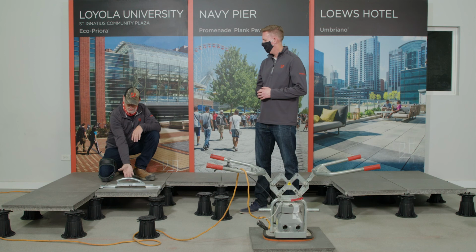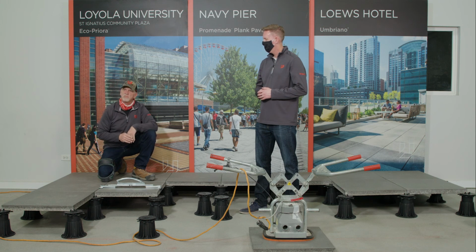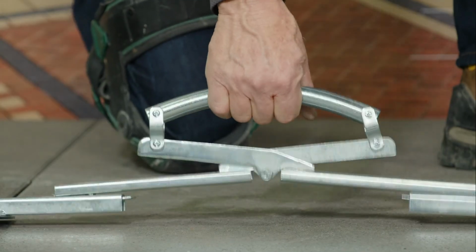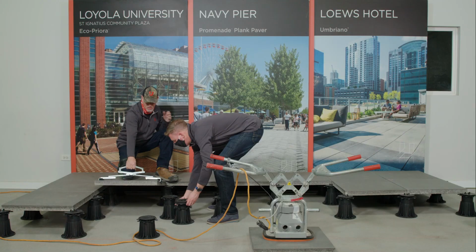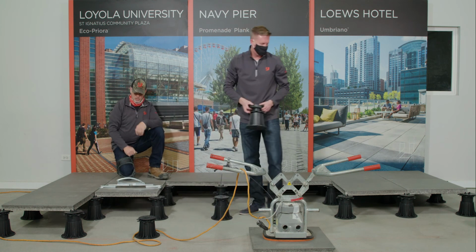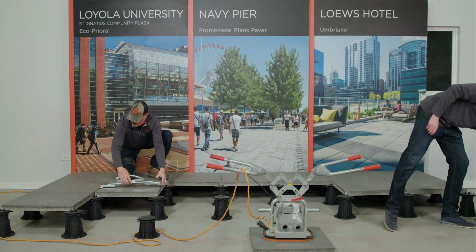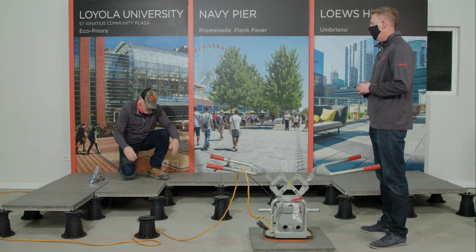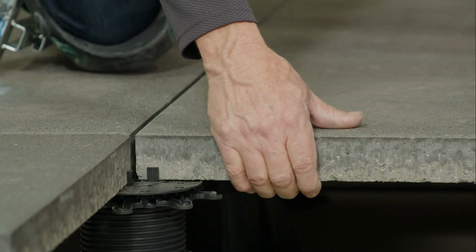Okay, when it comes to handling the material on the roof installation itself, there are various different tools available to the installers to assist them throughout the installation. I think this one is a more common, inexpensive piece of equipment, just a slab grabber, if you will. I'm going to lift this element up into place. It's just a scissors action, and Brad's going to do a replacement on that pedestal. That's just to demonstrate that. Now, the challenge I oftentimes see with this piece of equipment is that you need at least 1/4 of an inch on the spacing. Otherwise, you need to realign the slab once you use that.